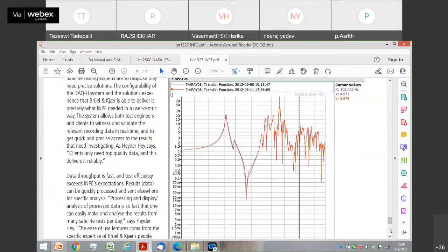When you are doing transportation tests, you could have recording either on a single axis or on all three axes. Measure all three axes of data, and then look at the road trials, wherein you could take this recorded data and run it back in a shaker to test the suitability of the structure, which means simulating in the lab the sort of vibration that the test object has undergone on the road.